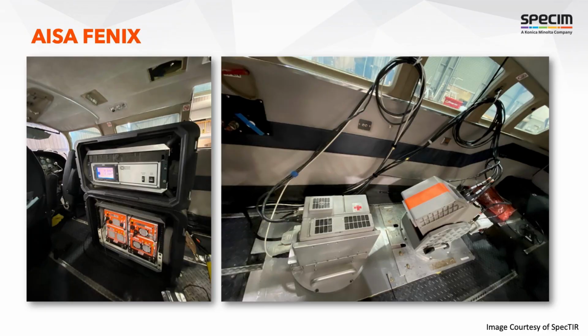This product has been developed mostly for airborne application, but it could be used as well for our SWIR rock for geological application. And here you could see how an installation looks like. So you can see side by side a Phoenix to record spectra between 400 and 2500 nanometers, as well as an OWL, which is a thermal camera to record spectra between 8 and 12 micrometers.